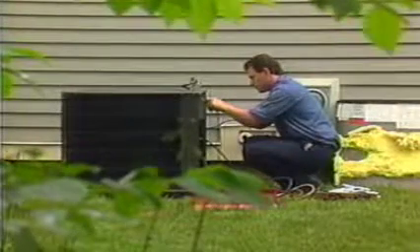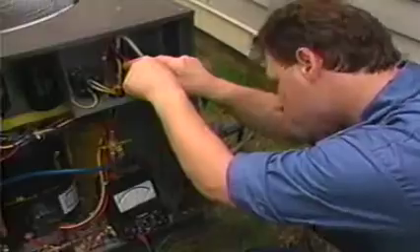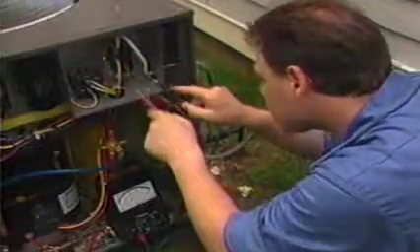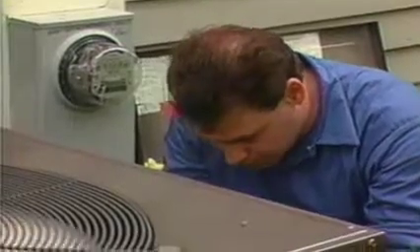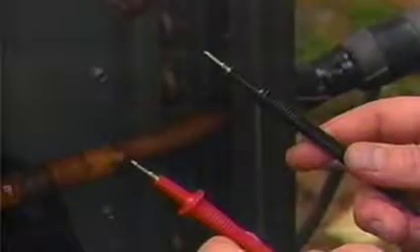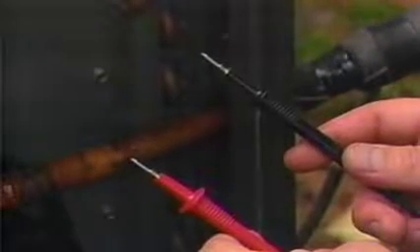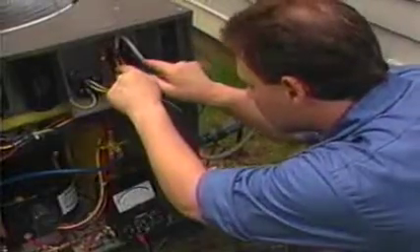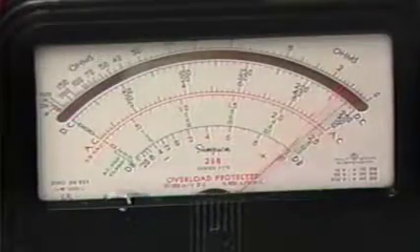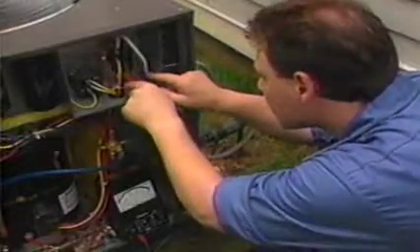As with gauges, the experienced technician will follow electrical safety precautions. Many times, a system will need to be inspected while the power is on. Use only insulated meter leads to touch hot terminals. These meter leads have stops to prevent the technician's fingers from sliding up and touching the terminals. Special care is taken when troubleshooting the main power supply panel. A screwdriver or other tool is never used in the energized panel.